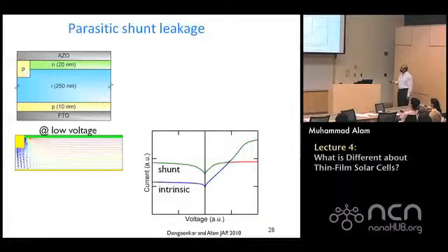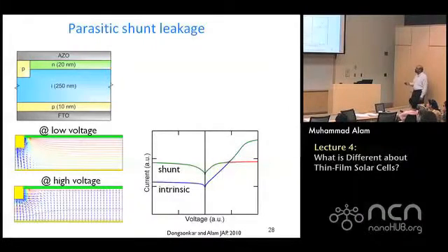At low voltages, what's going to happen? Most of the current is going to flow through this low resistance structure. At high voltages, of course, the diode will turn on, and then everything is fine. So at low voltages, this is the butterfly wing associated with this region, and at high voltages, of course, finally the diode behaves like a diode, and its value generally comes up. The reason being, this is a much larger diode. These are a few tiny regions, so therefore it can be higher only up to a certain point. Beyond that certain point, of course, this larger structure will show up.